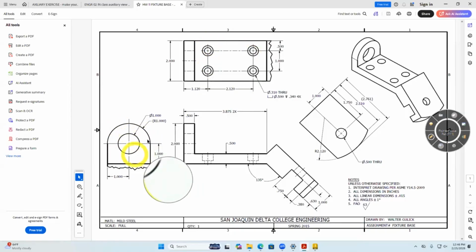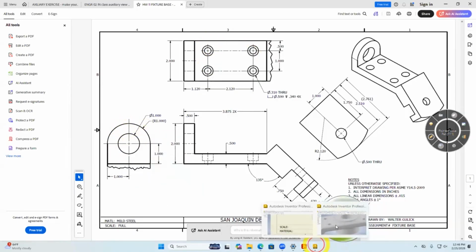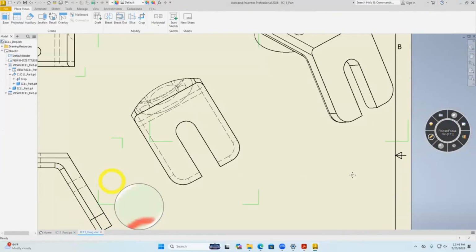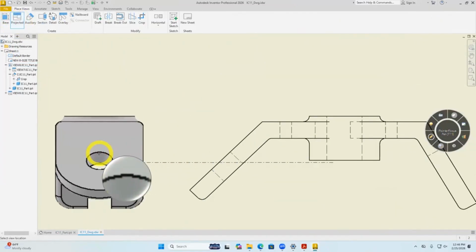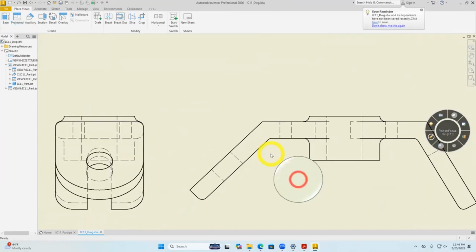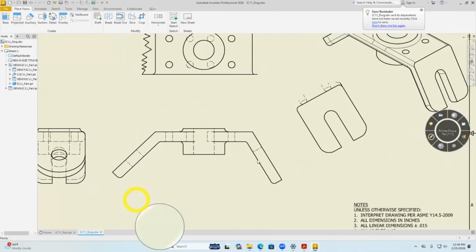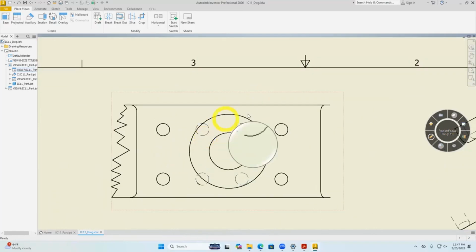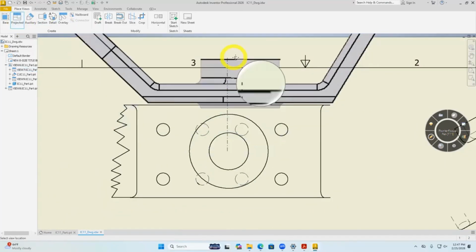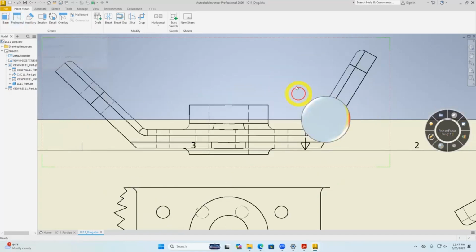You're going to create a projection view. You can create projection views too. When you have your view and you have placed it, you can create views by projecting it. This is a projected view. I can grab that view and then create a left view, right? Yes, see? You can create an auxiliary view. In fact, if I want to create another view, all I have to do is create projected, and then we'll create another view from the view that I started.